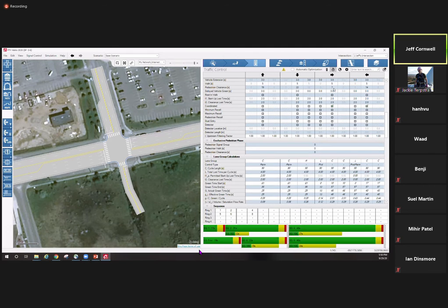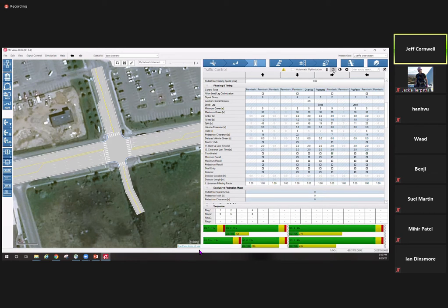So this first button, the traffic signal, optimizes your cycle and your split based on what you have. And if you click on the next one, that's when you can start going into the more complex optimization, such as changing cycle lengths. Or you have the optimize split button. If I want to optimize my splits here, that's the third one over. It shows a picture of what looks like a half-eaten pie. You would then select again, I would suggest the VC balancing, and then you click OK. In this case, it had nothing to optimize because it already optimized it. But if you change the cycle length, then you could actually use that again.